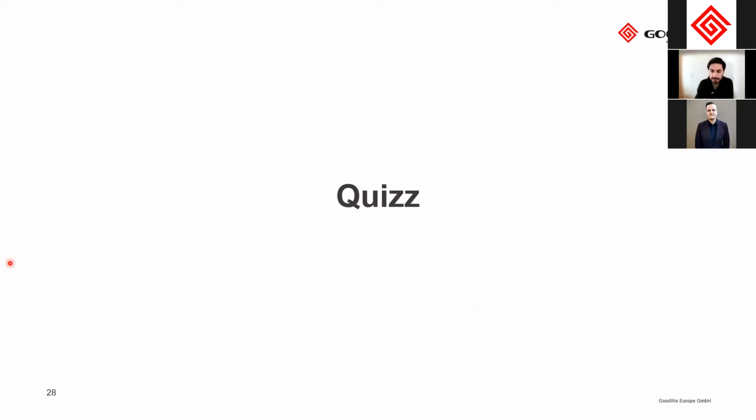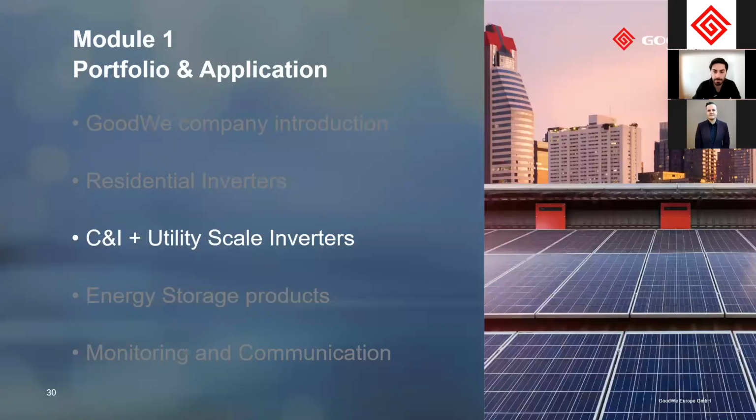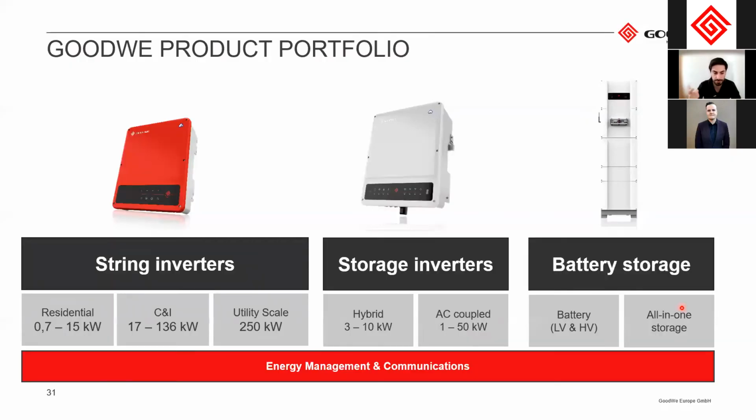But to answer your question, if there are any CTs for over 250 amps and above: our CTs handle up to 120 amps and are rather small, like the size of a dice. The cable size needs to be less than 16 millimeters in diameter.